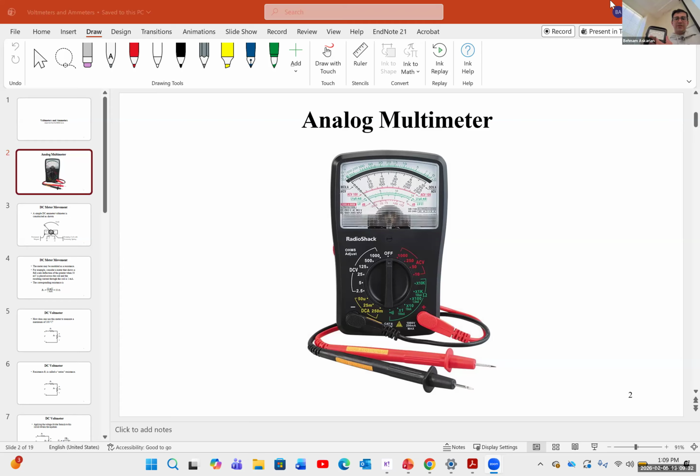After a while, when you put too much voltage through, the needle is going to move, what we call drift. And when it's not connected to anything, it's not going to go back to zero. Therefore, we have to adjust that screw to push it back to zero. So you have to constantly calibrate this. Again, it's very, very sensitive to movement, to mechanical shock. Even if you do a measurement when it's standing up, and when you lie it down, you're going to maybe have some errors as well.